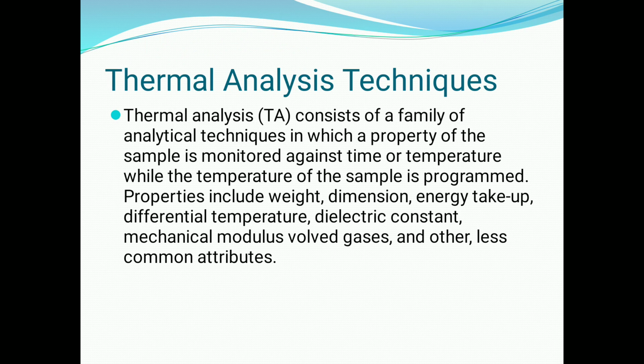And the next test is thermal analysis techniques. Thermal analysis consists of a family of analytical techniques in which a property of a sample is monitored against time or temperature while the temperature of the sample is programmed. Properties include weight, dimension, energy uptake, differential temperature, dielectric constant, mechanical response, gas evolution, and others having less common attributes.